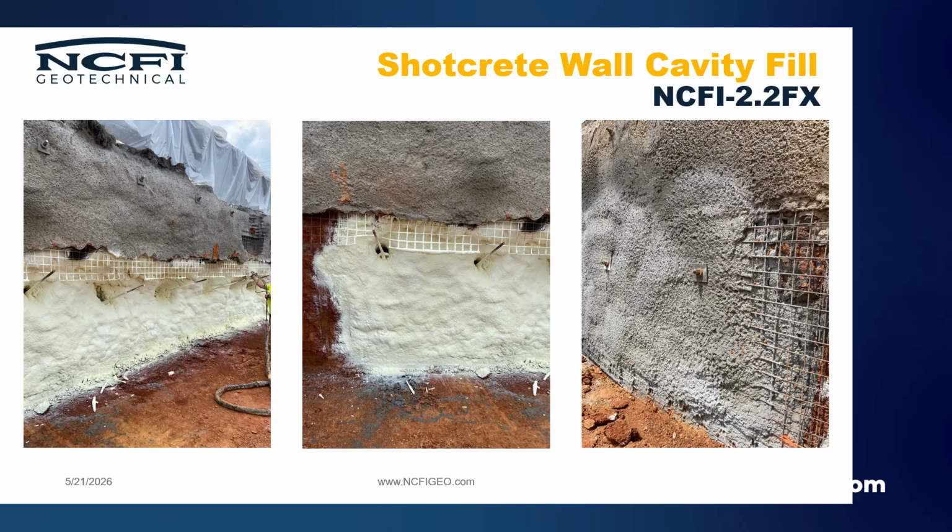Would have to be done a little bit differently. And with the foam, it's lightweight. The desire wasn't necessarily for this to be structural. It's not locked in, but because it is the spray system, it'll attach itself to the dirt pretty well. Then they'll put more wire mesh up, and as you see on the far right, they sprayed right over it. We had no adhesion problems with the shotcrete.